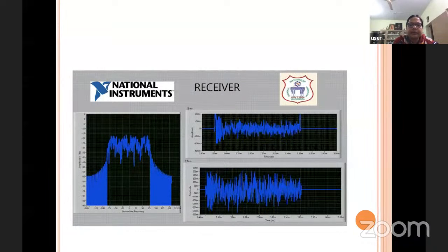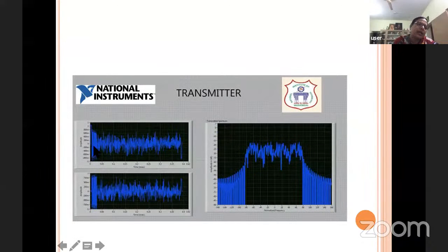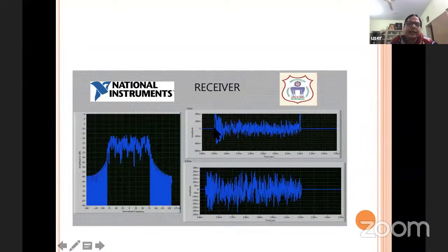So this is my receiver. We can see that from the transmitter to the receiver, the transmission is started exactly at the 0th point, whereas the reception starts after a certain time. But for my decoding scheme, I don't know whether I have to start decoding at the 0 point or at this point, because I don't know when my received signal is arriving at my receiver. So what exactly do we have to do? We have to estimate this null time. After estimating the null time, from that time onwards, we start decoding the signals. So this is what we have done in our communication laboratory.